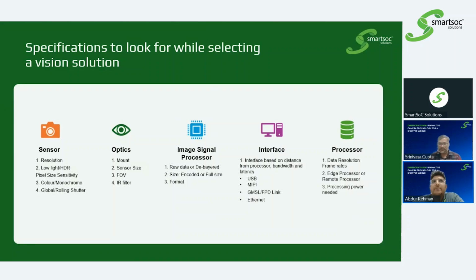Understood. So there are certain sensor parameters like dynamic range, sensitivity, or resolution. These form the major selection criteria based on your application. For example, if you want to capture large data at a higher distance, and you want crisp, accurate data, then I believe resolution is important because you want the image to be broken down into smaller parts so that clarity is there. And then it depends on what kind of lighting conditions you are using. If it is broad outdoor conditions, then probably the dynamic range comes in.